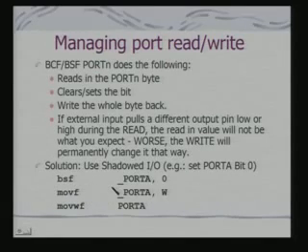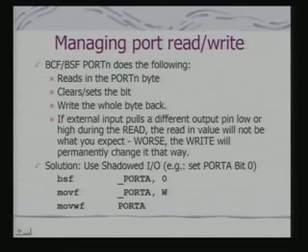Now there is another problem associated with the code. Let's look at this. Read, modify, write instructions enable us to implement the critical region, but there are also some issues involved here. Just imagine that you have read and then there is an external input which pulls a different output pin low or high during the read, because read takes some finite clock time. So the read-in value will not be what you expect. In other words, the write will permanently change it that way. Because after the write to the port, these bit values would be changed, and changed permanently.